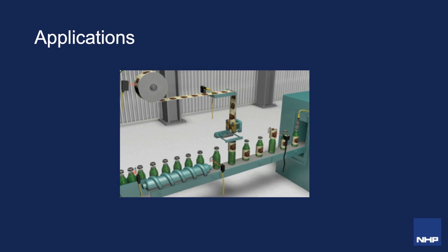So the first point, we are detecting if the bottles are overfilled. Now here, this is completed via a retroreflective sensor. Now we can see that the liquid appears to block the light through the bottle completely, and there is space on both sides of the bottle for placement. Now, if the liquid level is too high, the light beam is blocked and the current retroreflective sensor detects this. But this could also be done through beam sensors.